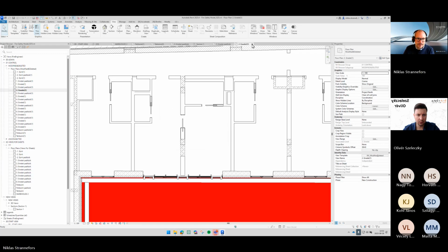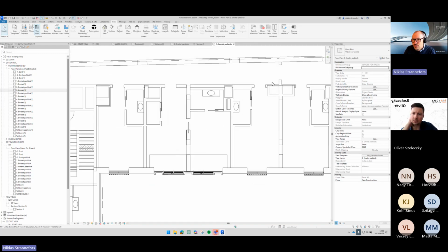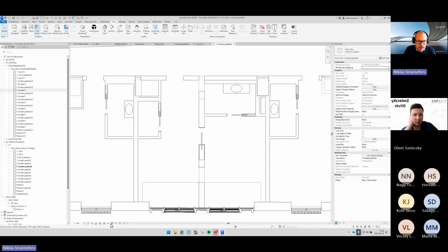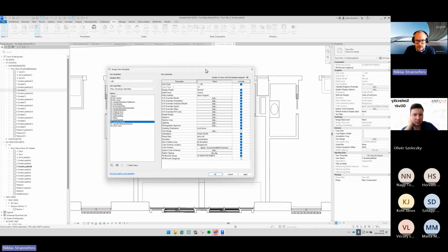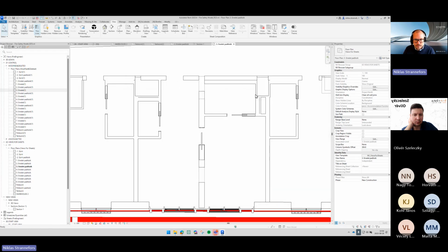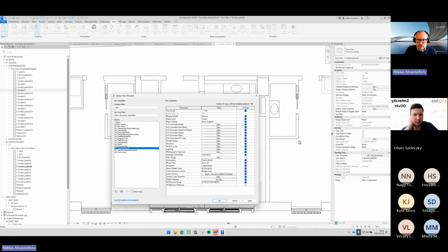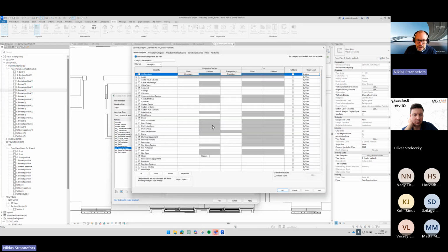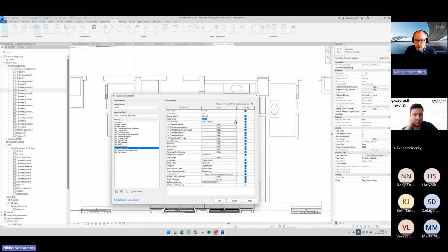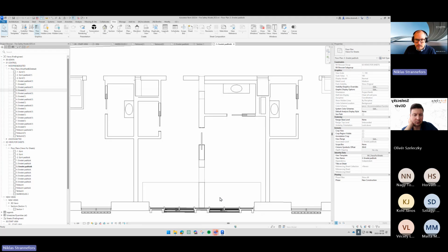How they show the doors depends on how they built the door component. I need to double check one thing, I actually didn't look at this beforehand. We can go back here for views for sheets and change how we look at doors. I want to change the detail level from coarse to medium, so we go back to the view template, change it, and press OK.